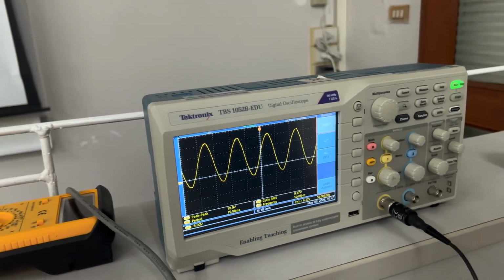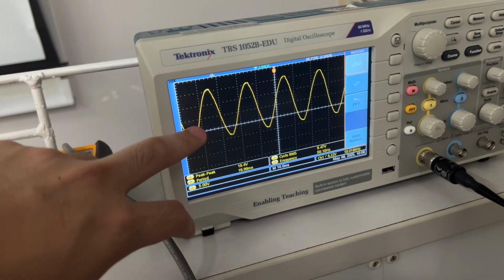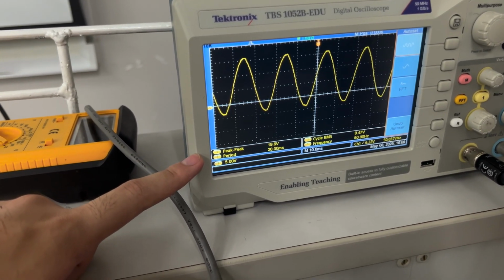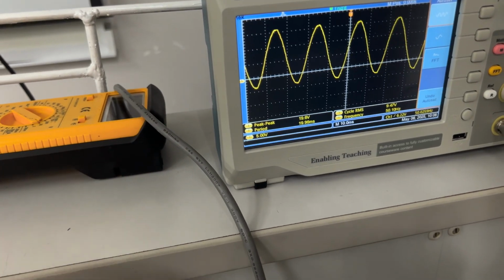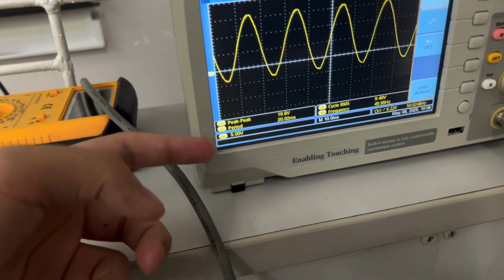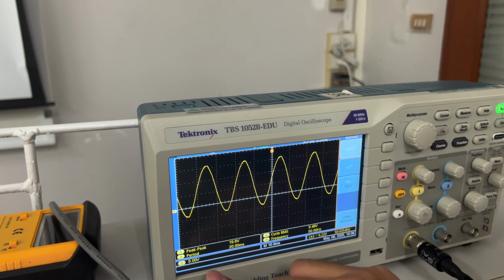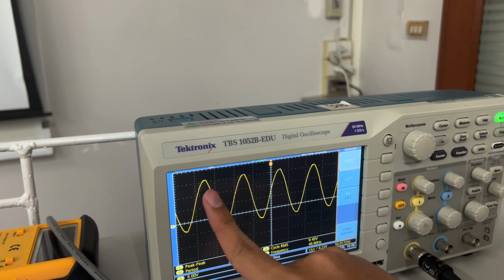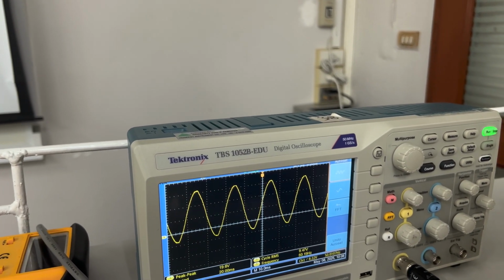So this waveform is two time divisions, which we can see from this box, which is two boxes to a full waveform. The voltage peak is 20 and the period is 20 millisecond per one period, and the voltage scale is 5 volts per division. So how to count the division, is one division right? So it's around 3 point something. 3.8.